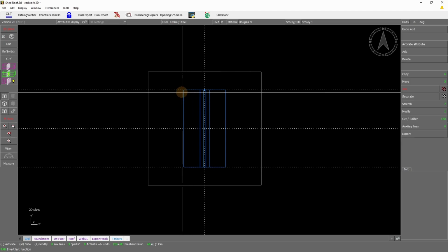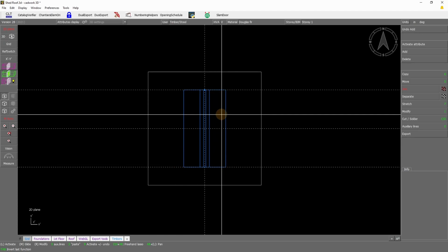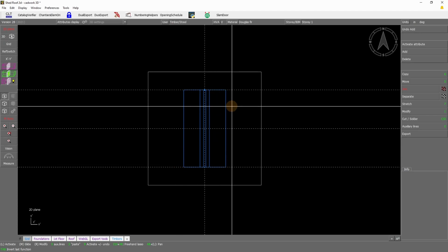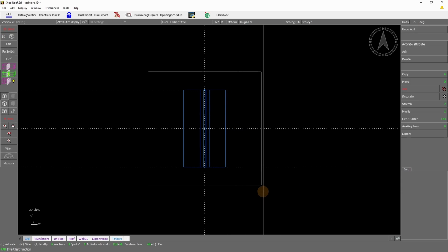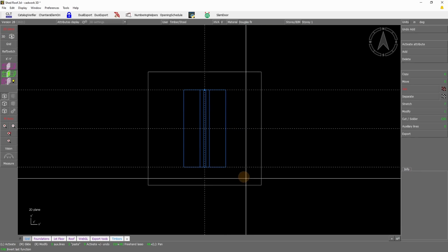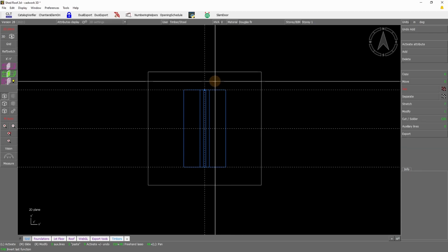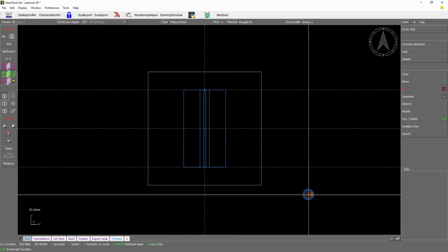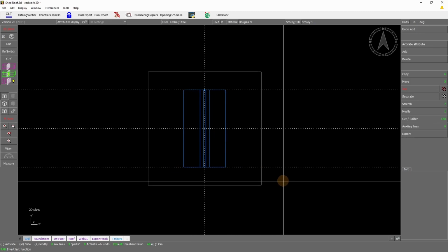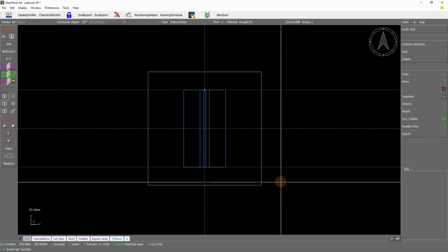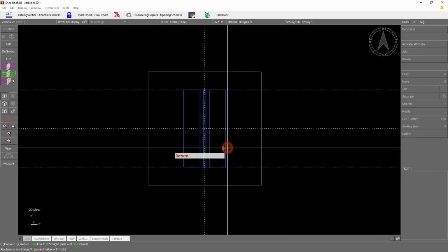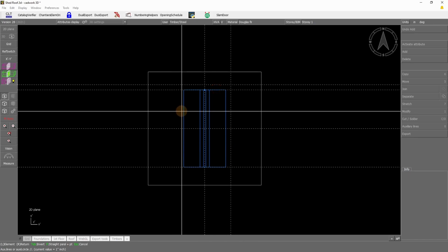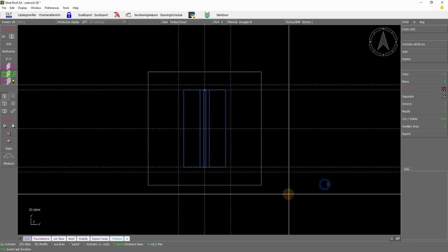And here we will add directly the second concrete base. It is 1 inch high and needs to go 1 inch around the base, since it has a 45 degrees chamfer. So E for offset line 1, enter, and here we'll simply use the outside of the steel shape as reference.